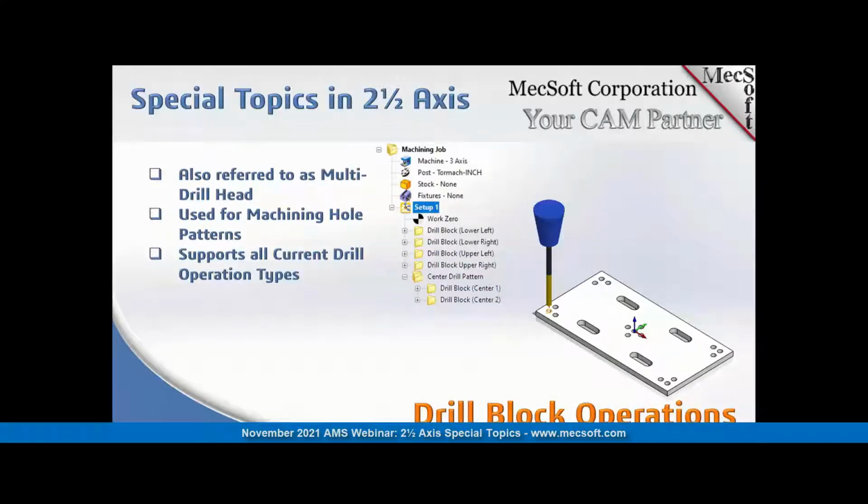Next slide. Now, this is going to be a really interesting topic. If you're cutting a lot of holes in a production setting and a lot of hole patterns, you can get a drill block, also referred to as a multi-drill head, set to this pattern that you need to machine. And we're going to show you how to set that part up and use the multi-drill block to machine the part that you see here.